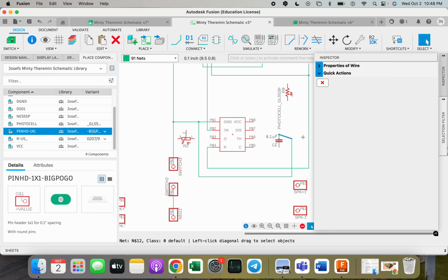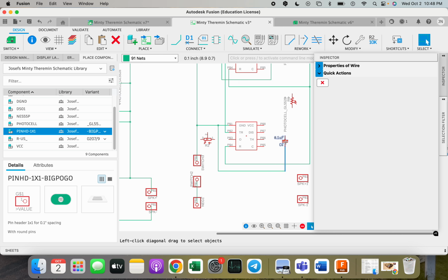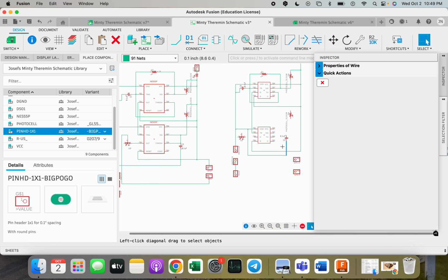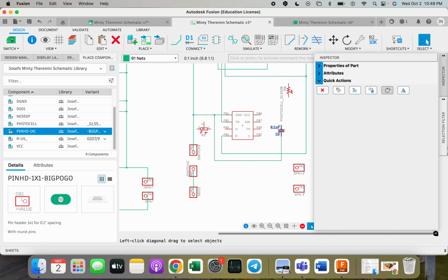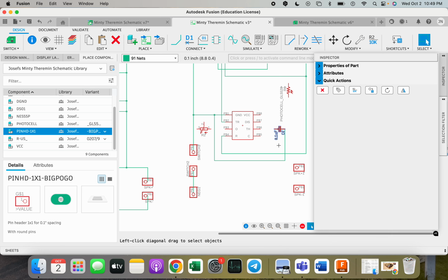I don't like the way that the pins are going, so I'm just going to remove those lines and drag this one and attach it to the bottom there. And we'll move this capacitor. Actually, I like the way that this is with the smaller 555, so we're going to turn it back sideways, and we can take this line and move it over so it's nice and clean.